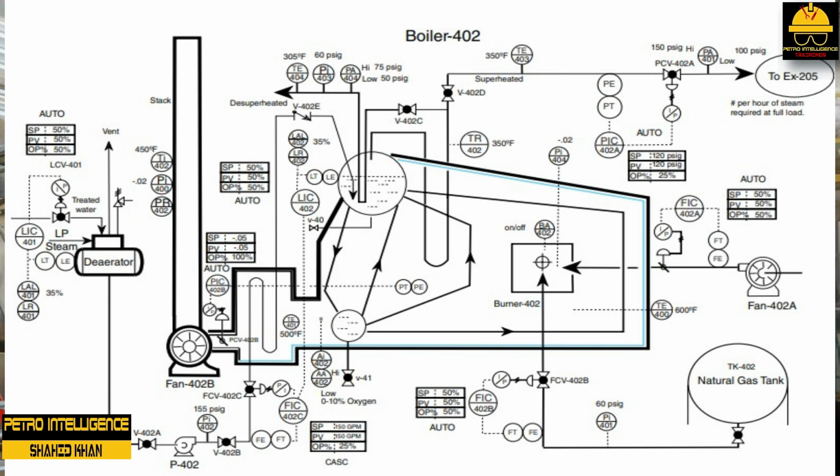The pressure on the water sets the temperature as long as the steam and water are in contact. Basic boiler design removes the steam from the upper steam water drum and superheats it at essentially the same pressure. B402 is designed to operate at 120 psig.